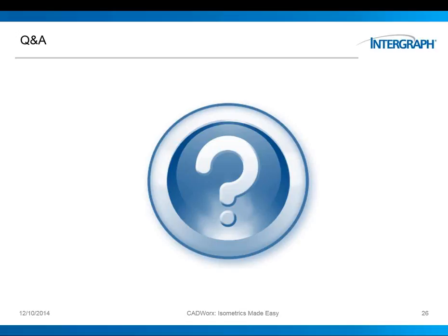Thank you. What is a stress isometric and how do I create this? The stress isometric is basically a modified version of the normal isometric. Instead of a material takeoff or bill of materials, which is normally printed on the right-hand side, we have results from the stress analysis package. So this could include forces and moments, displacements, support reactions, code stresses. Isogen and iConfigure are included in every seat of Caesar2. So the stress ISO basically allows you to convey the underlying geometry as well as the stress analysis results without the need to print out a thick report.